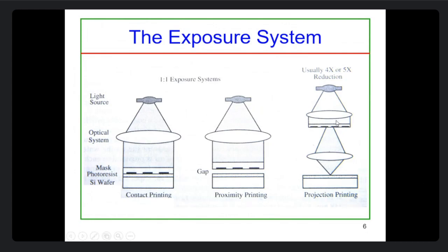So there are some imperfections, as I mentioned, lenses are not perfect. Of course, your mask or reticle is also not perfect. But mainly here I am trying to focus on the lenses, because we have two lenses. This optical system is much more complicated in comparison to these two. So the whole optical train or system is not perfect. There are imperfections in the lens, some kind of irregularities, in the sense of aberration, some kind of distortion.